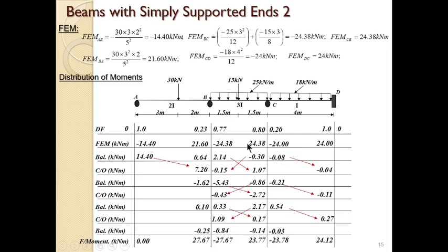You do the same here: find the excess load, introduce a moment, and find the excess moment, and introduce a moment of the same magnitude but opposite in direction. Distribute it to these two members meeting at that joint based on their distribution factor.